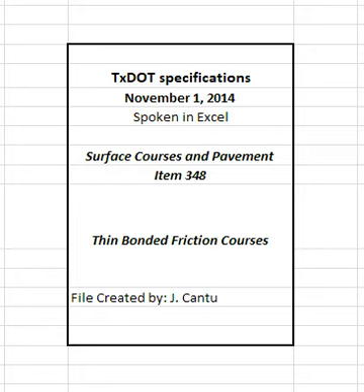Provide the engineer with split samples of the mixtures before the trial batch production, including all additives, except water, and blank samples used to determine the correction factors for the ignition oven used for quality assurance testing during production. Correction factors established from a previously approved mixture design may be used for the current mixture design if the mixture design and ignition oven are the same as previously used unless otherwise directed.